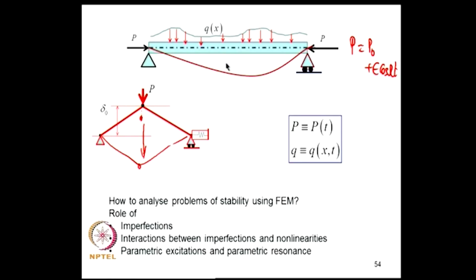So, these are not the traditional resonances, but special types of resonance known as parametric resonances. There are many systems in engineering practice where we get problems of this kind, and they are characterized by structural matrices which vary in time. So, for these time varying structural matrices, the questions on parametric excitations and stability of the structure also need to be considered.